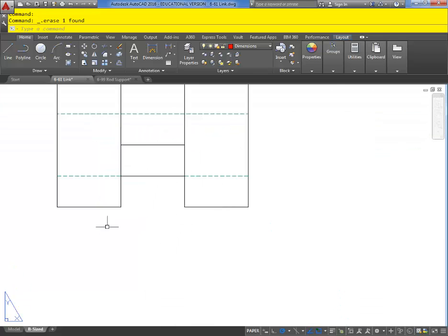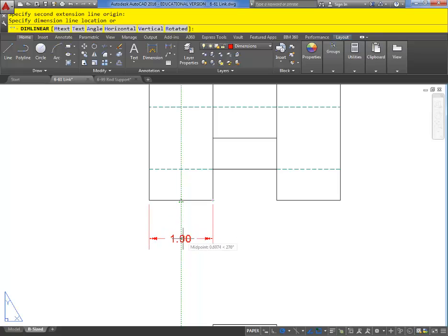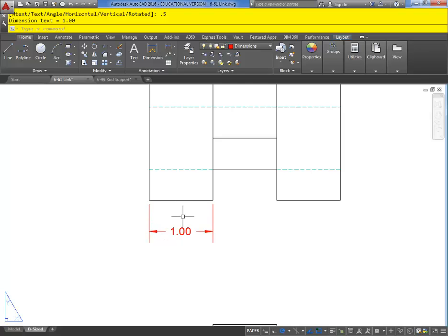So I'm going to go back to my baseline dimension idea on this one. So as I said, the first dimension needs to be a 1/2 inch off, and sometimes success tracking off of the part, and sometimes it goofs up on me, so we'll see what happens. So as I'm coming to place this one, I'm just going to track off of the midpoint, drag away from it, and go 0.5. And this is now 1/2 inch away from it.